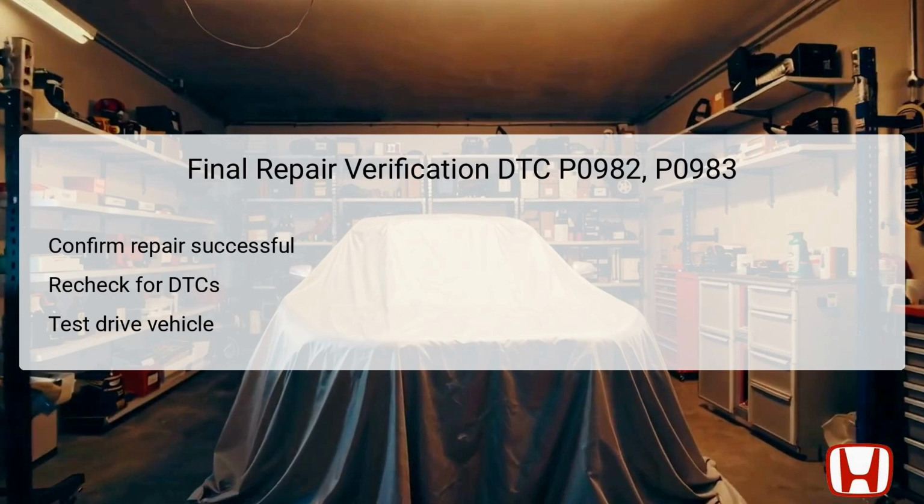Subsequently, recheck for any DTCs using the HDS tool to confirm that no new or persistent codes appear. Once satisfied with the diagnostic results, conduct a test drive of the vehicle to verify proper transmission function. During the drive, observe the shifting behavior and monitor the performance closely. If no issues arise and no codes are displayed post-test drive, this indicates successful resolution of the identified faults.